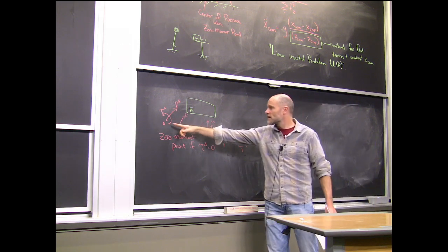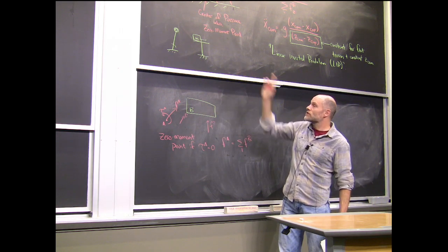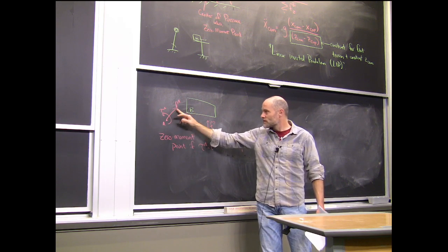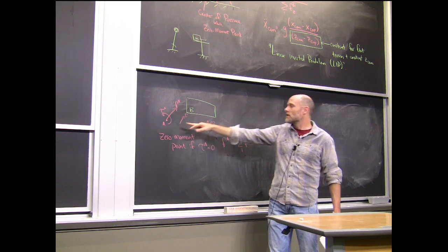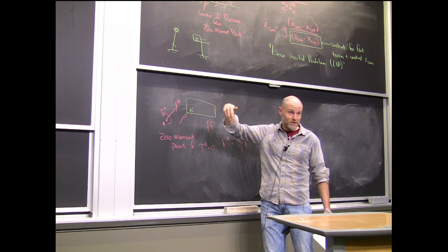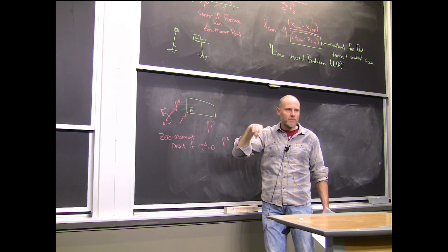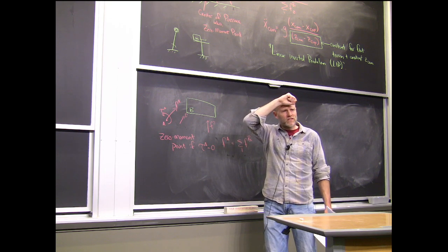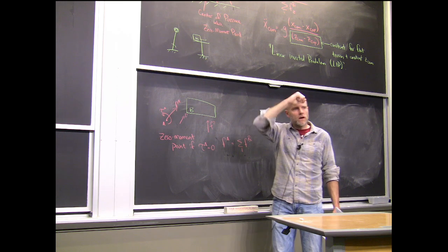You wouldn't be surprised if the zero moment point, if this reaction force starting from the zero moment point goes through your center of pressure, then you also have no angular momentum change. There's a bunch of geometric properties like that. What does the line look like? I haven't thought about that. There probably is a geometric interpretation. I just haven't thought about it.